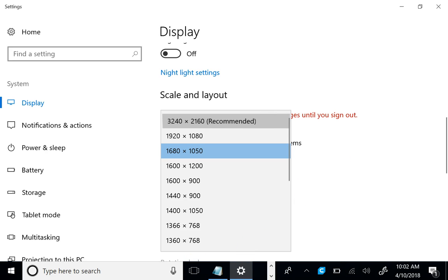And you won't have this problem if you don't write an STL by hand. If you write it in CAD, it'll keep the units with it most of the time. Every once in a while, you'll find a shape that somebody coded in inches, but left the millimeter tag in there, and it'll show up mega tiny. So there's my kind of shape, right?